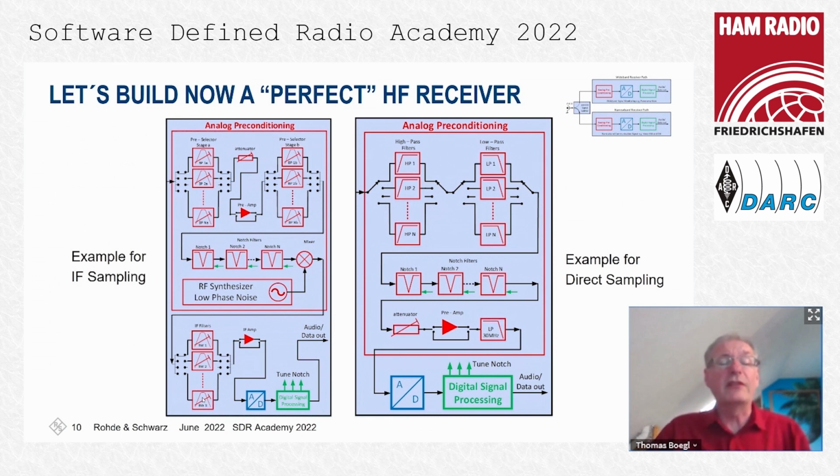We keep it as close as possible and as wide as necessary. And we have the choice to use different IF frequency values like 69 or 70, a bit more, a bit less, just to avoid any mixing products, depending on the selected frequency for the complete receiver path. So the difference is mixing and filters, and the difference is also seen in the data sheet.